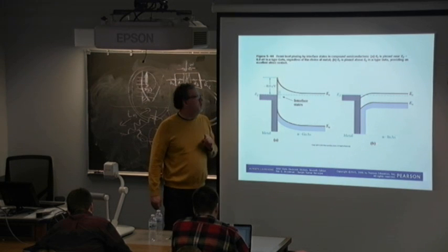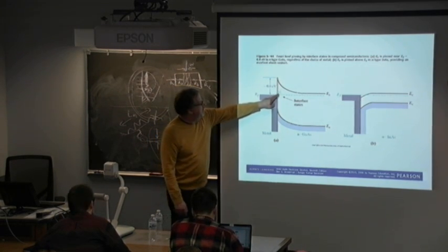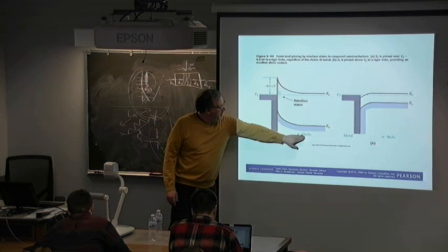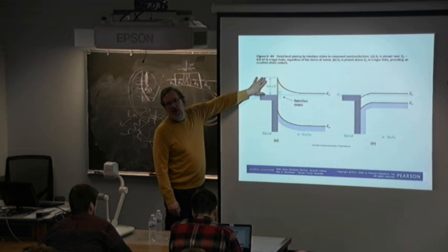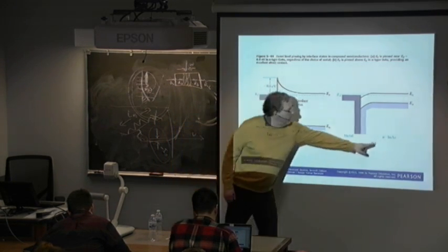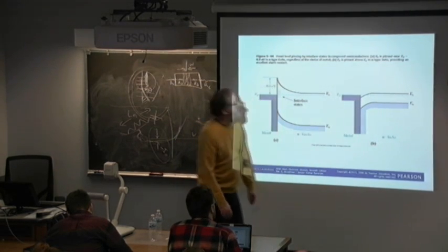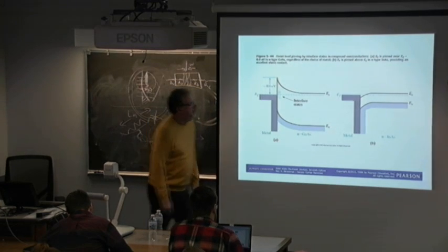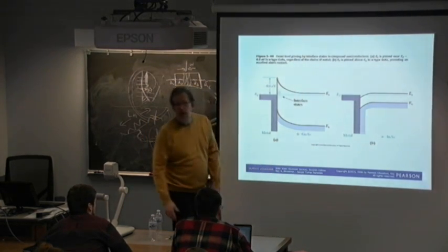The terminology we use in our field is that it pins the Fermi level, so that no matter what you do with N-type gallium arsenide, you get a 0.8 electron volt Schottky barrier height, no matter what you do. Indium arsenide is actually more forgiving: no matter what you do, the Fermi level pins in that way, and so therefore for electrons to flow, there's really no appreciable barrier there.